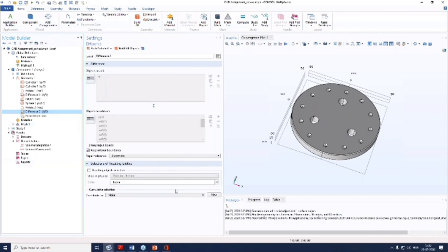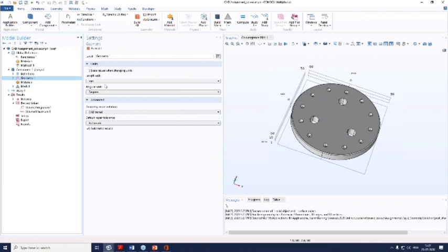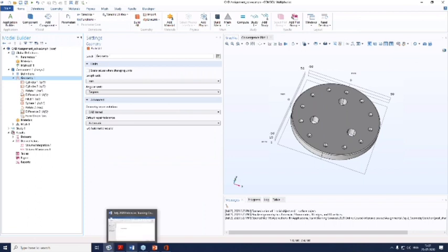Everybody is going to take automatic, and automatic will be decided based upon the dimensions that you have as well as the geometry. But if there are any really very small features, or if you are building any high aspect ratio geometry, in those cases there might be a chance that the smaller entities may get removed, or intentionally in some cases you want to remove the entities, and in those cases you will have to provide that tolerance manually.